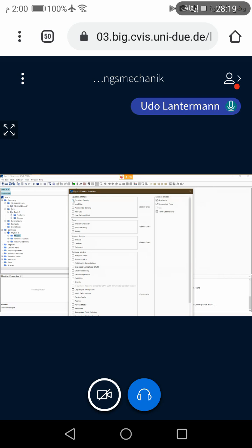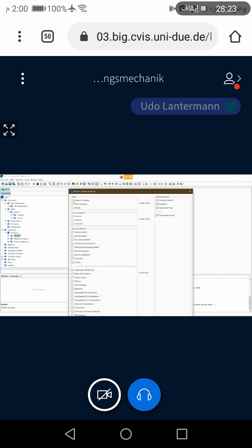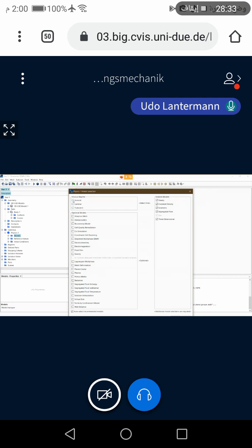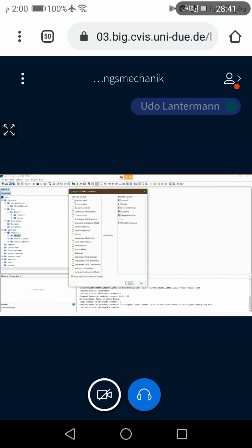And next step is constant density. Then we choose a steady simulation. And our first step is the inviscid one, so choose the first option of the viscous regime, it's inviscid.